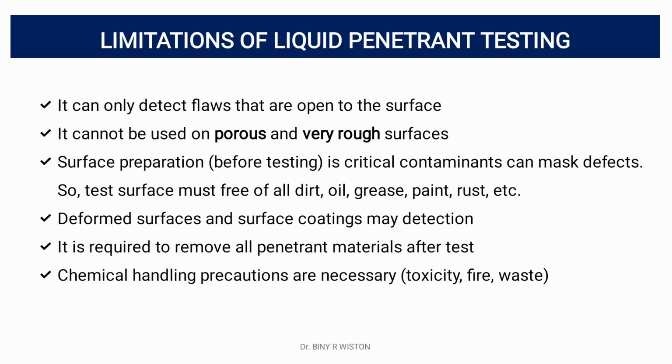Then the limitations. It can only detect flaws that are open to the surface, and it cannot be used for porous and rough surfaces. Internal flaw detection is unsuitable through LPT.